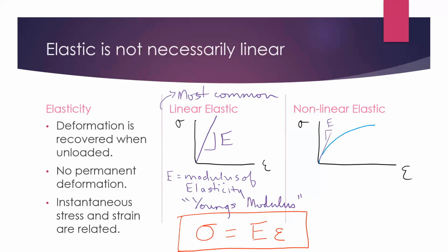So that only applies to that linear class. The form of it being written like this only applies. Let me rephrase. What you just asked, the answer is yes. This equation only applies to linear elasticity. And then what I started to answer, which was not your question, is does that only apply to uniaxial loading, which is the one direction of loading? And the answer to that is yes. We have a more complicated form of this equation for when we have loading in multiple directions.